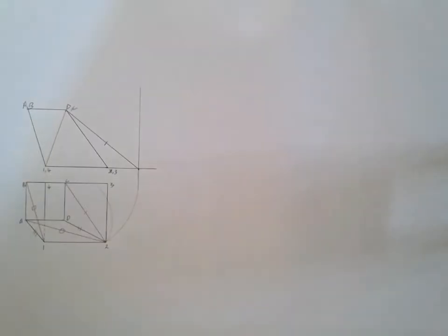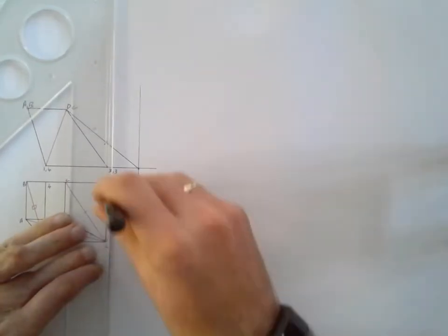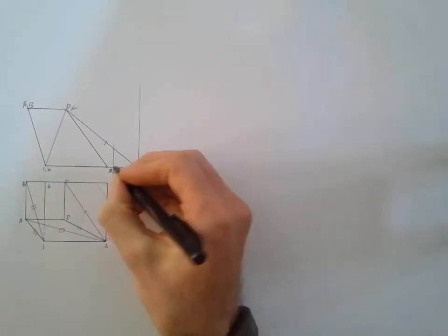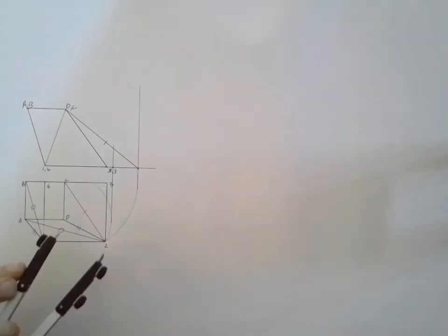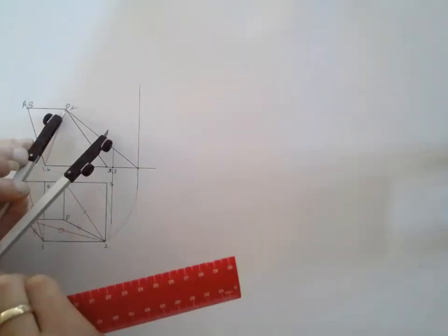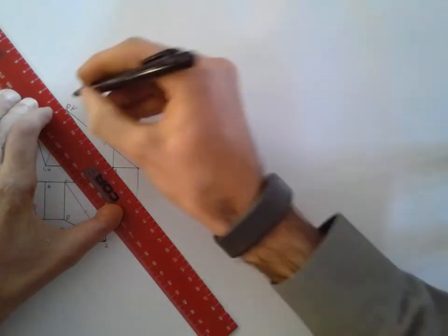Take the edge of that arc, project it up, and again you've projected a base point, so where it links up with the base here we can mark that point. And again you placed your compass point on point D, which is in line with the same point that you joined your last true length to, so we're going to again join that point up to point D in our front view.